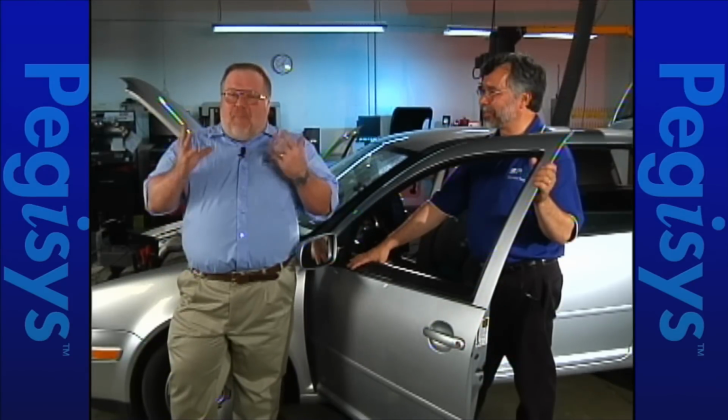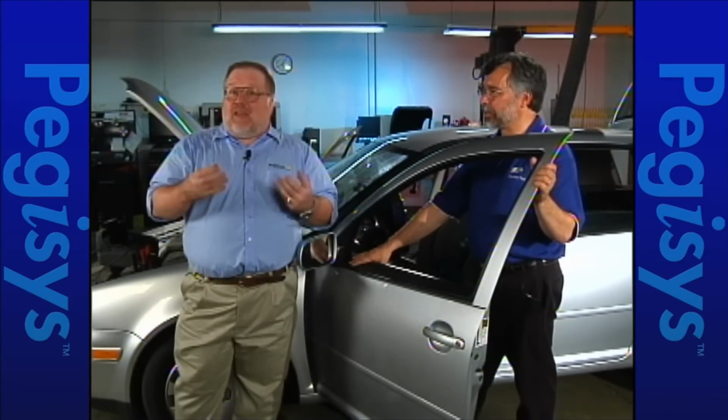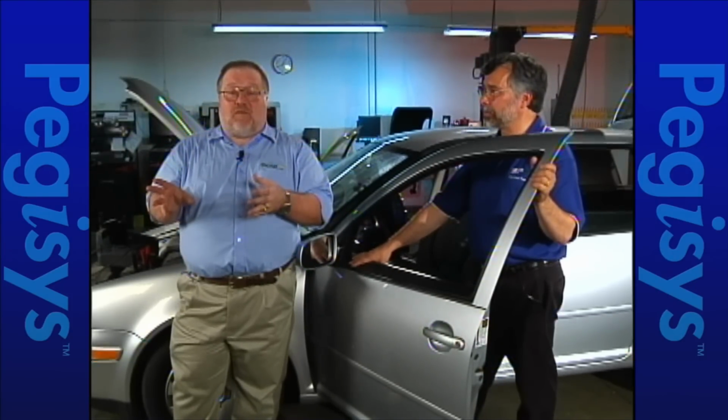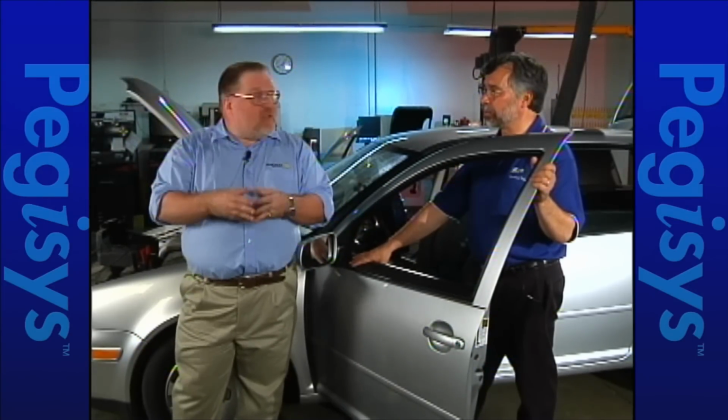Okay, based on what we have seen and what we have tested, it's looking like we're going to have a faulty front O2 sensor. And obviously we want to take care of that problem before we even think about doing anything with the catalytic converter. So my conclusion is, based on what we've done, we're looking at a faulty front O2 sensor. Steve, what do you think?